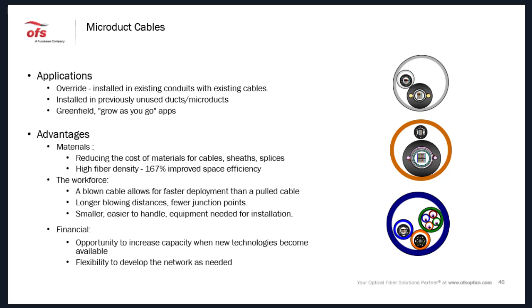The advantages are very huge because they have many advantages: materials, workforce, and financial. So, reducing the cost of materials for cables, sheets, splices. For the workforce, the cable could be blown to a longer distance. That means that we need fewer junction points, and we need a smaller handhole, smaller junction splice box. And for the financial, it's an opportunity to increase the capacity whenever there is a change in the technology, and whenever we want to make an upgrade on our network.